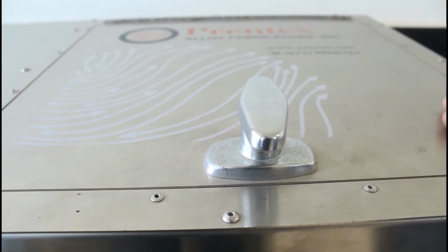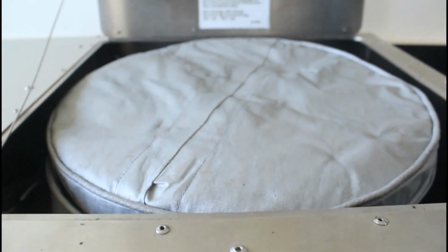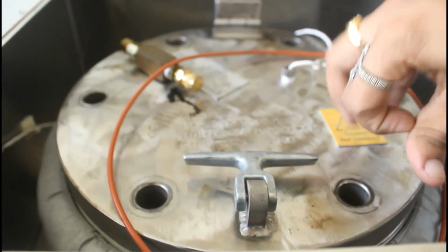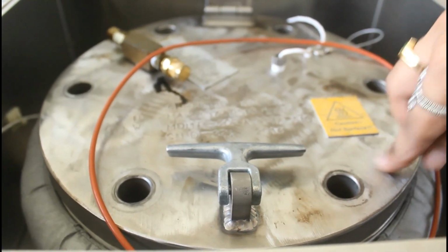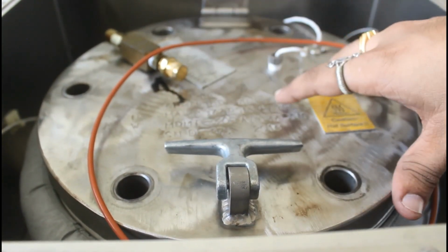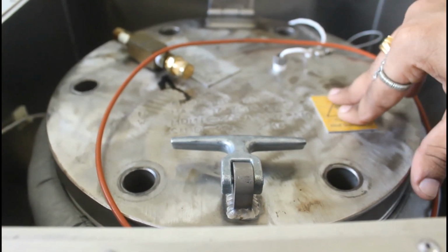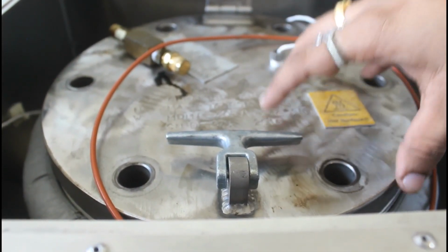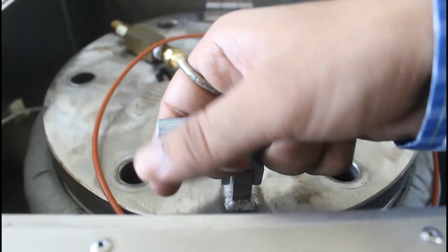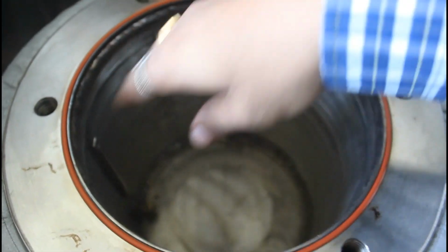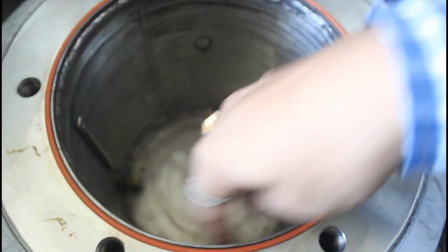So this is the PAV. This is a lid, and this is the pressure aging vessel. You can see how thick the chamber is, and this plate is very heavy because inside this chamber we will apply a pressure of around 2.1 megapascal. You can imagine it's a very high pressure, so this vessel should be able to sustain that pressure. It is very heavy also, and you can see how thick this particular chamber is.